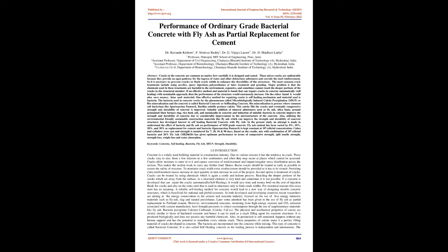The most common crack treatments include using acrylics, epoxy injections, polyurethanes, or latex treatment and grouting. The major problem is that the chemicals used in these treatments are harmful to the environment, expensive, and sometimes cannot reach the deeper portions of the cracks in the structural member. If an effective method and material is found that can repair cracks in concrete automatically, self-healing, with a sustainable approach, then the performance of the structure would enormously increase. On the other hand, it would also save money, time, and material.